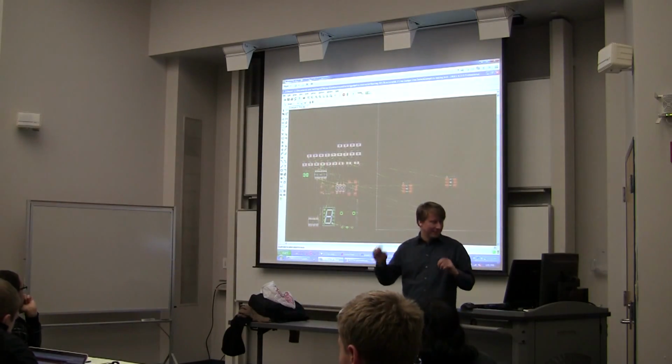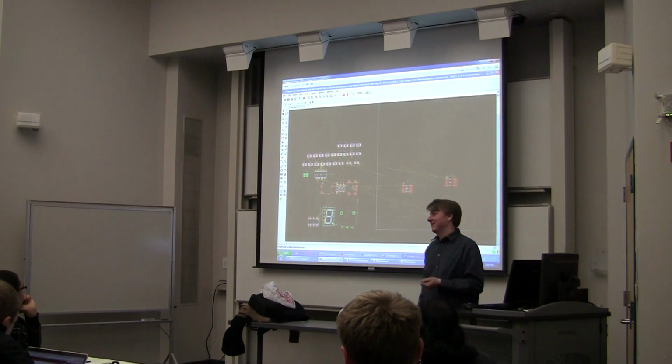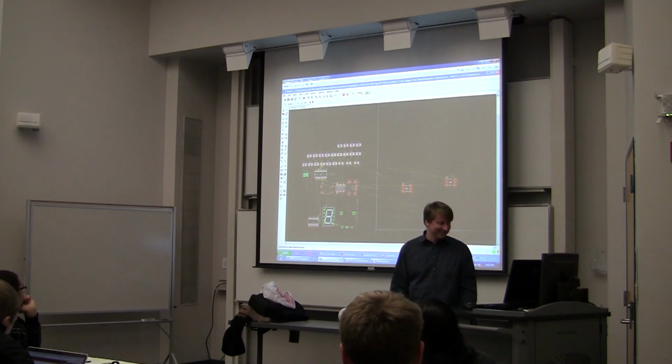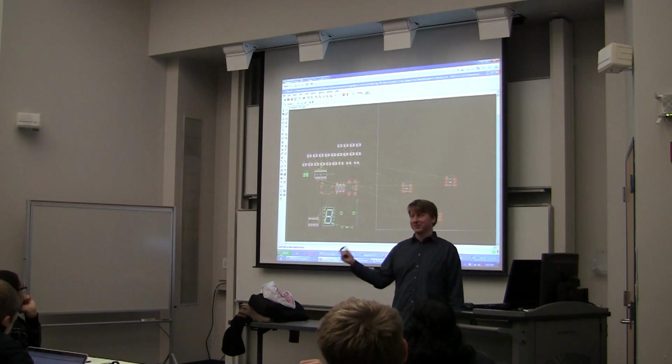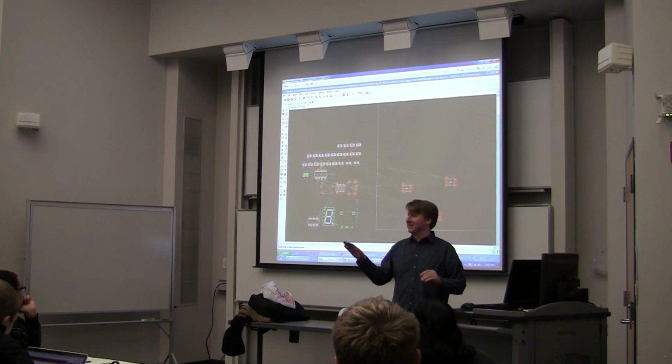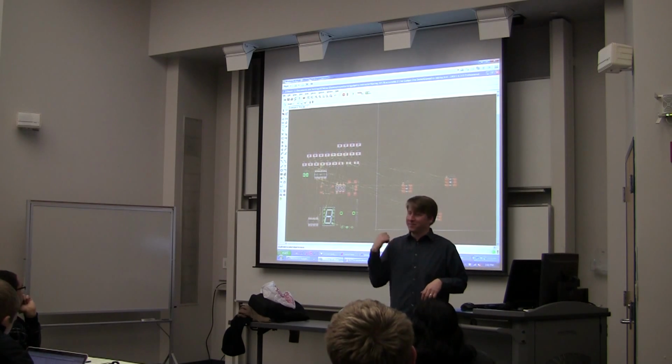What? Well, that's what happens when you use binary to BCDs. You need a lot of resistors. You could also use one resistor on the common anode, but then, depending on how many LEDs are on, it's brighter or dimmer. This is the more appropriate way to do it.